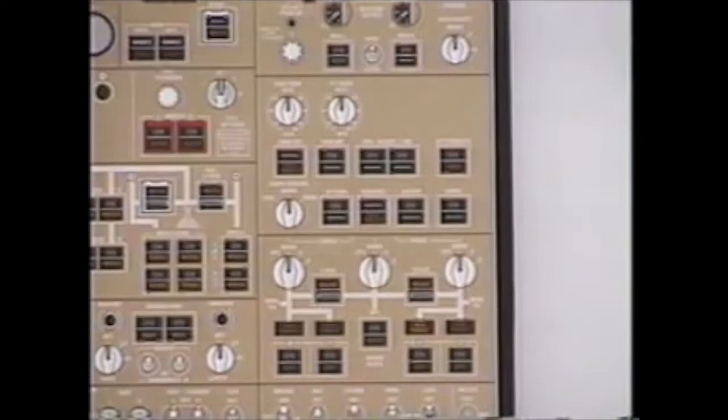So if a step climb was to occur between top of climb and top of descent, the packs would be in normal flow. If any pack for any reason shuts down, the remaining packs will instantly go to high flow. To determine a flow mode of your pack at the current time, bring up the ECS synoptic. Above the pack circle will be indicated high flow or nothing for normal flow.